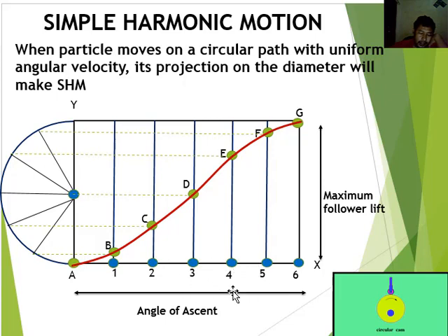After that, divide the angular displacement of the cam during the stroke and return stroke into the same number of equal parts. So you can divide the angular displacement like this of the cam during the stroke.